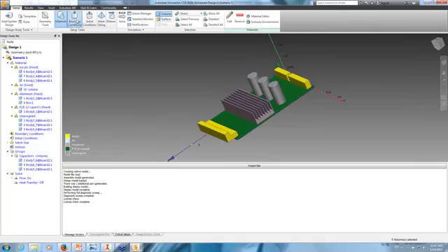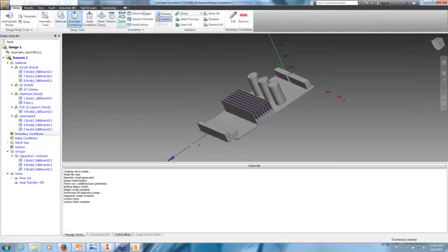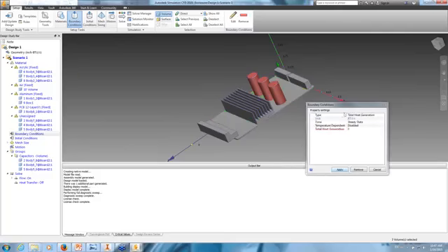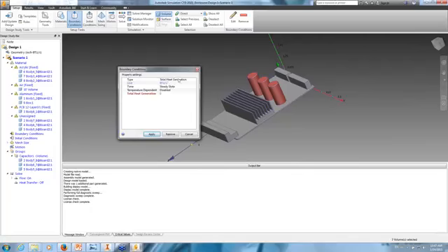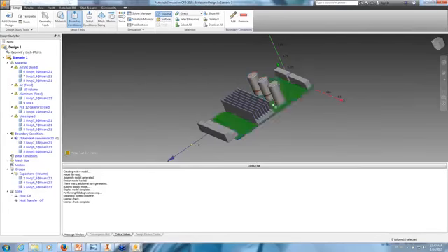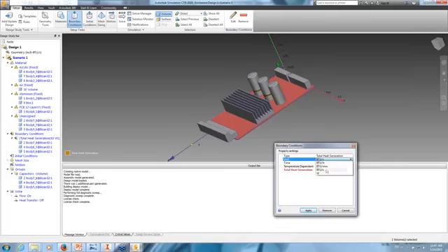Next, I'm going to click on boundary conditions, and I'm going to select by volume. Select these three here and specify total heat generation. Let's make that watts. Let's say 10 watts. So each one of these will be generating 10 watts. And let's say there are other components here that I'm not modeling, and this one is going to be generating some heat as well, maybe 20 watts.